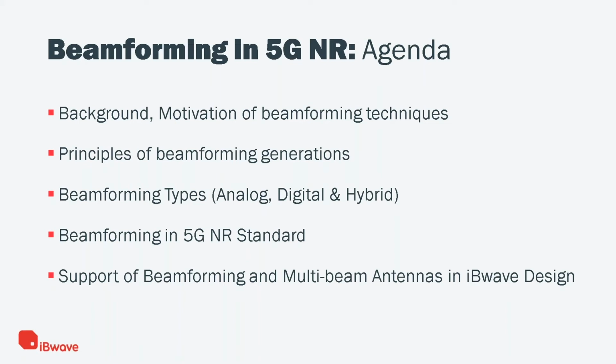So we will discuss the difference between analog, digital, and hybrid beamforming. Then we will tackle how beamforming is specifically applied in the 5G new radio standard. And finally, we will go briefly through the key modeling aspects of beamforming and multi-beam antenna in our IBWave design tool.